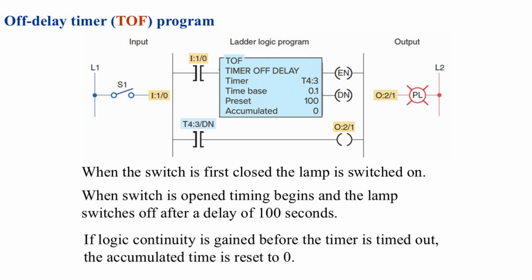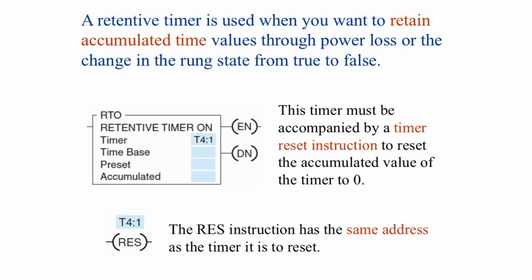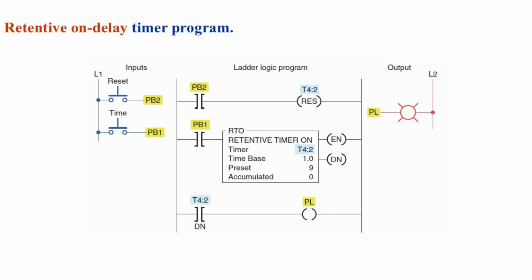after a process stops. A retentive timer accumulates time whenever the device receives power, and it maintains the current time should power be removed from the device. When the timer accumulates time equal to its preset value, the contacts of the device change state. Loss of power to the timer after reaching its preset value does not affect the state of the contacts. This slide shows how a retentive on-delay timer, or RTO, works in a programmable logic controller ladder program.